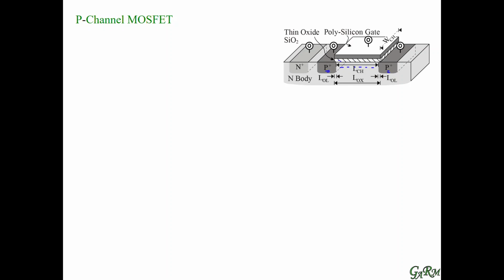We also put an insulating oxide region here, and that's because we want to build a capacitor that connects from the top of that region to the region immediately underneath that gate oxide. And that's what's going to induce current flow.